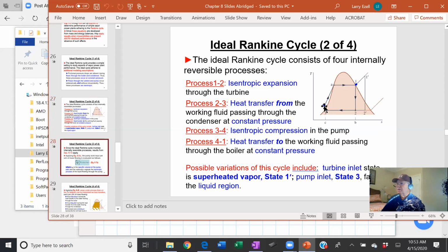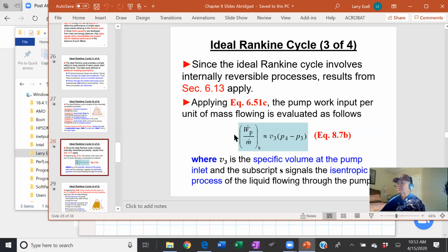So there is another way to calculate the isentropic pump energy, and it's the v dP. So you look up the specific volume, and I could write out the energy equation for a liquid and show you how this is derived. It's not that complicated. It's just hard to do it here without a board. Just accept my word for it that this is very legitimate.